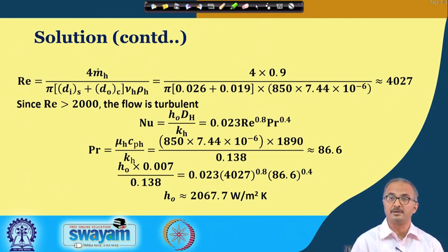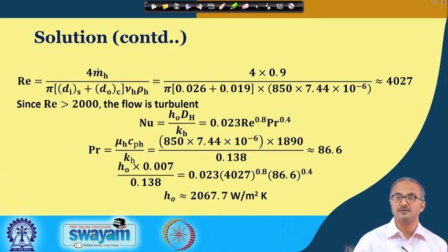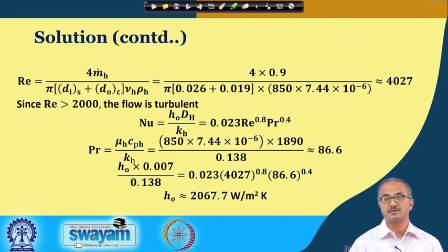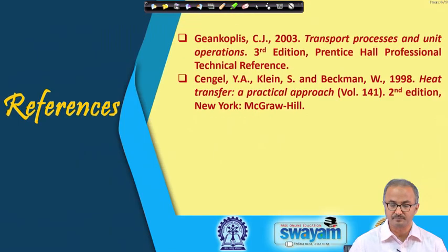For example, for laminar flow, had it been less than 2000, then you should not have used this equation, you should have gone for the Sieder-Tate equation. There is another equation for circular pipe, Sieder-Tate. So those kinds of equations should be used for laminar flow. So this is very crucial whenever you are finding the heat transfer coefficient, mass transfer coefficient and the friction factor.